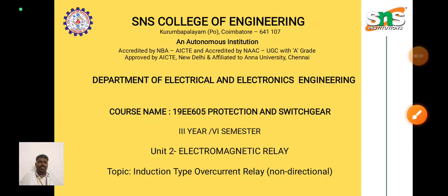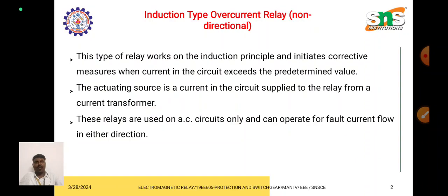Hi everyone, welcome back. In today's class, we are going to see the induction type overcurrent relay, the non-directional type. This type of relay works on the induction principle and initiates corrective measures when the current in the circuit exceeds a predetermined value.